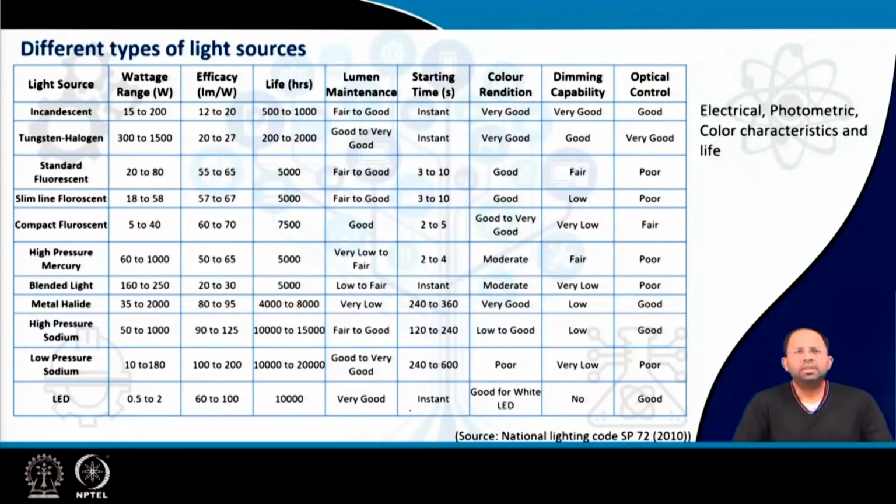Now, this is a list of the different kinds of light sources that we usually use in urban areas, starting with incandescent light. This is the basic, older light source. Now we are replacing them with other kinds of light, particularly fluorescent light. And there are different types of fluorescent light. Usually in India we are replacing them with T5 fluorescent lights. T actually stands for tubular, the shape of the light, and the 5 refers to the diameter or size of that particular light.